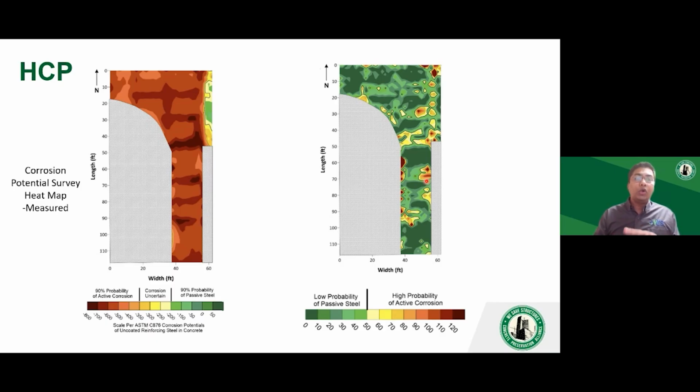You're having coating to coating contact, or in some cases where the coating is completely gone, coating to steel contact. So the prerequisite for this kind of survey is that your rebar is electrically continuous, either by means of ties or stirrups. If your rebar is electrically touching each other, you can easily do this survey. So assuming that your rebar is electrically continuous, just one connection per element or one per entire concrete deck should easily work for you. And this hole is like 5/8 inch diameter, or half-inch diameter in some cases.